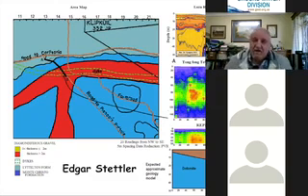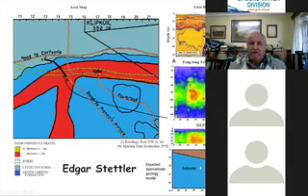We can see that the first survey was done down to 150 meters, where you select your spacings. You can go 100, 150, 300, whatever the case may be. But then I had another special unit that can only look 50 meters deep, and the repeat survey was done at 50 meters deep. If you compare the repeat survey with the radar and the expected proximate geology model that has come out, there is a very, very good correlation of the data.